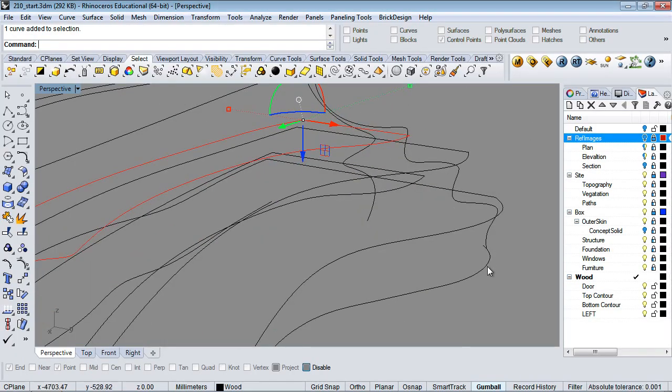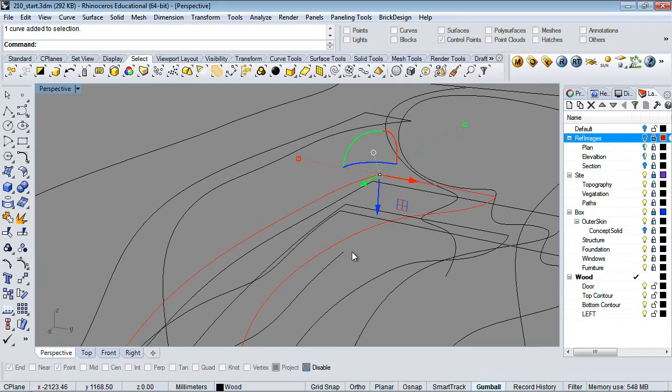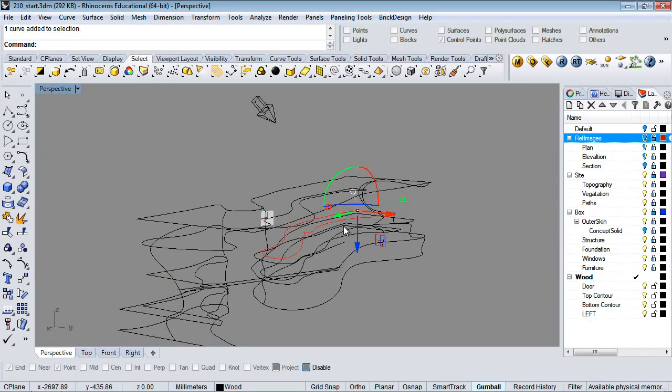This will be my bottom rail. And then this section between here and here is going to be my cross-sectional curve, because then I'll sweep that piece and it'll go around. And then I can create this upper piece separately. And again, thinking about if I use rail, you could use a patch on this one, for instance, and then cut out the holes where you want it to be the rail.